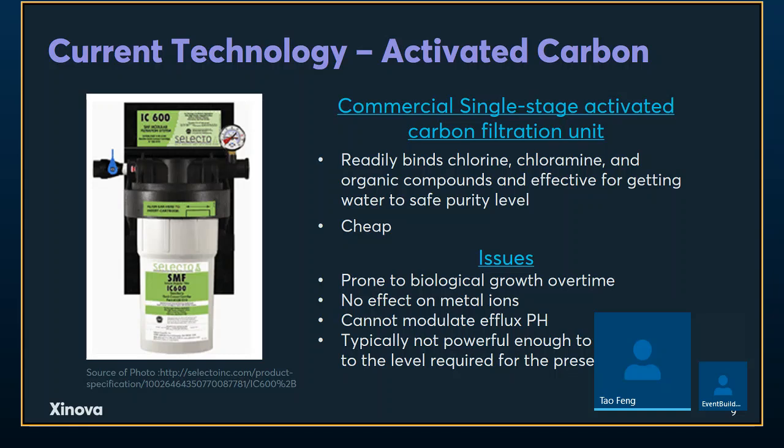Activated carbon we're all very familiar with. It's a porous carbon material, which is ideal for non-specific absorption process. Activated carbon is very commonly used in all kinds of water purification applications, but it's actually not powerful in terms of removing metal ions, especially lead. It also has very low or even no absorption affinity for salts. That will be a concern for the soda fountain application because too much salt in the water can cause a lot of problems.